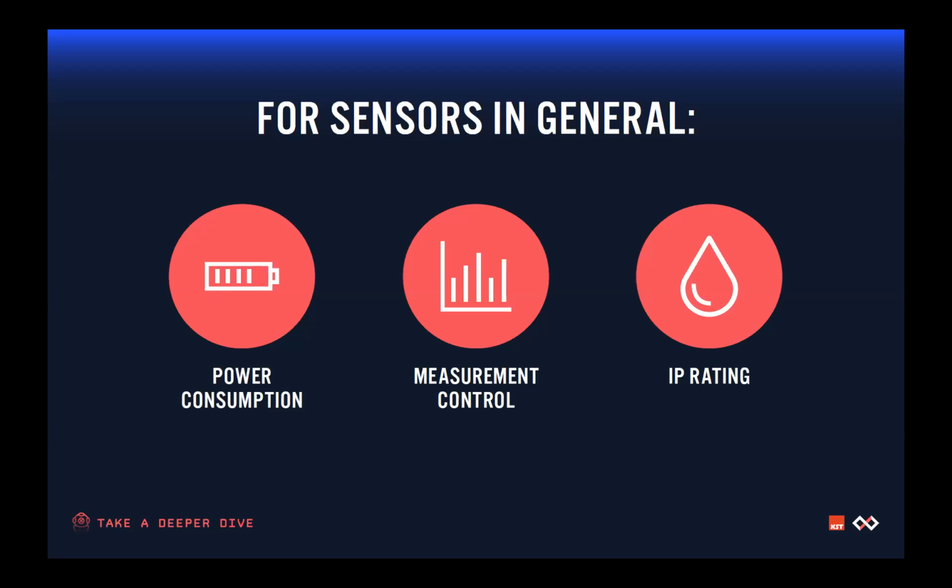You should also think about whether or not you can control that IoT sensor in the field. In the case of the KST 3320, we do support downlinks. A really common scenario for our customers is to start off by pushing a lot of data to the cloud. And then they realize, the trash can really doesn't change that much over the course of an hour period. How about we just do 1 measurement an hour? The nice thing about the KST 3320 is you can send that downlink to the device, and then you can change its uplink, which is really great to have that level of control. And this is fully integrated into Losant. We can support downlinks that communicate directly to our sensors.